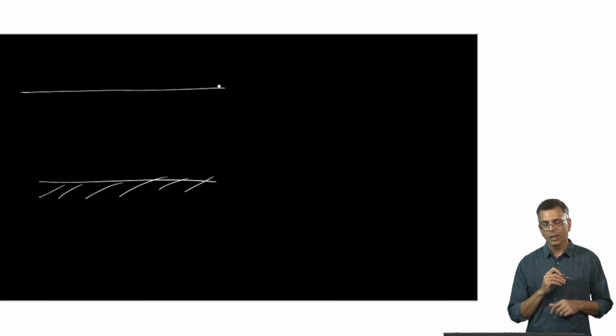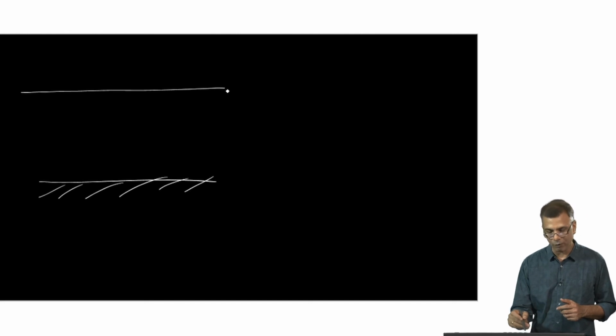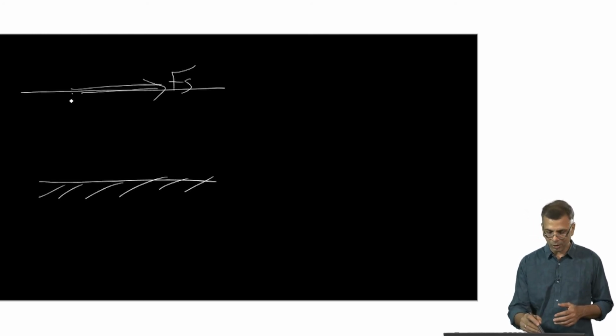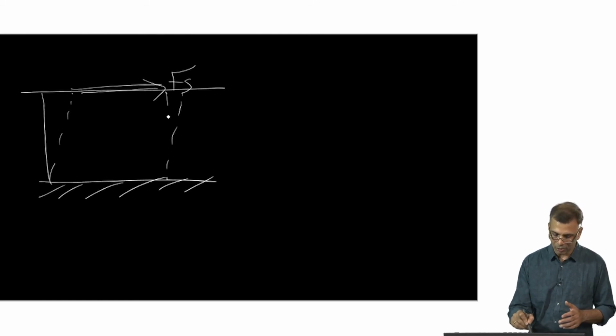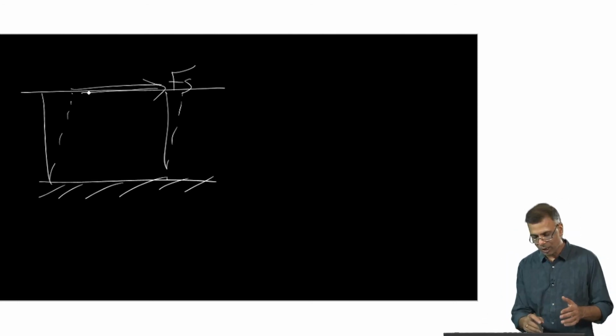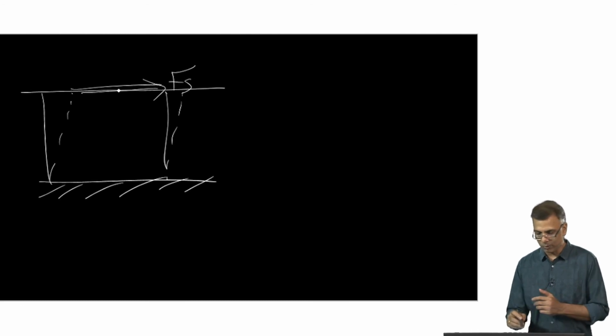And imagine a container of a fluid with a surface like this, either a solid or a fluid. This is how you differentiate: you apply a stress that's along the surface, in other words like this, you apply a shear stress like this. Now a solid, as you would imagine, would be distorted, but not that much. It would distort a little bit like this, but it would tend to snap back to its original position. It would snap back, right? Whereas a fluid, on the other hand, will not be able to withstand this shear. It will flow.